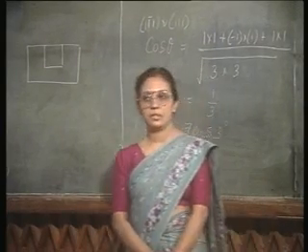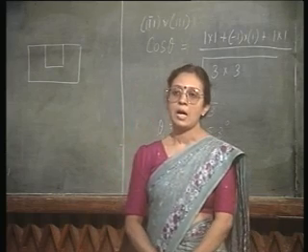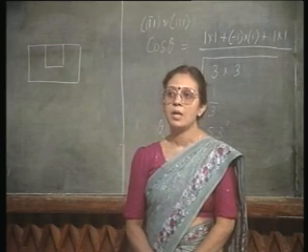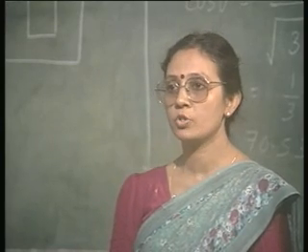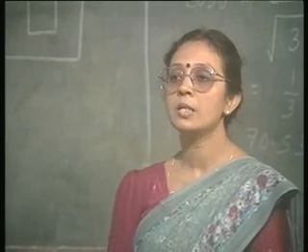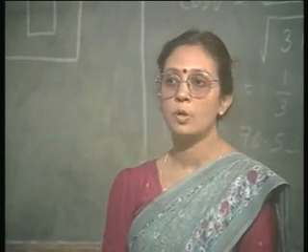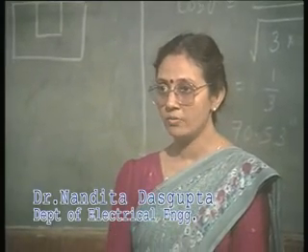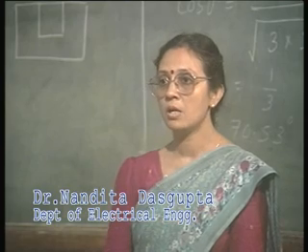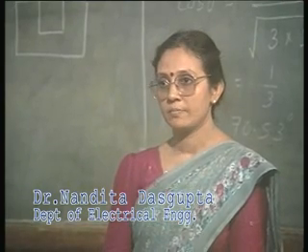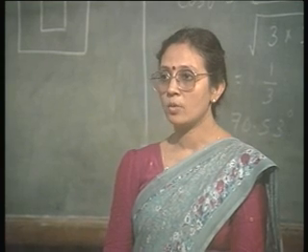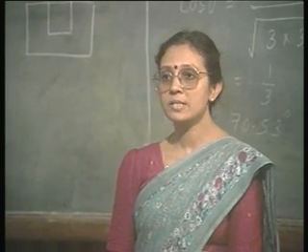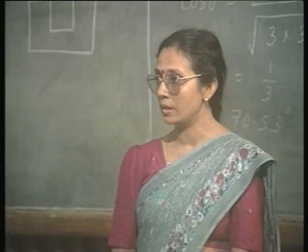Finally, let me tell you that there are some other processing steps like oxidation and diffusion, which will also be influenced by the properties of these individual planes. For example, the atomic density. You have noticed that the atomic density was lowest in 100 plane.